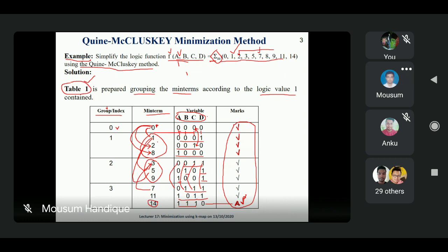All the other parts remain the same. And why is this symbol required? Because when you are constructing the PI table, you can automatically understand that this 0 with a star means 0 belongs to the don't care. All the other comparing parts are the same.